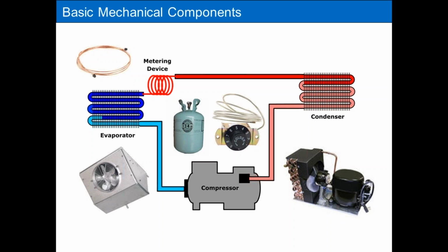It has a basic temperature control, but one thing I want to make sure everyone is clear on tonight is that the temperature control that we'll be discussing senses coil temperatures, not air temperatures. The way these systems generally operate is the unit is controlled by monitoring the coil or evaporator temperature.